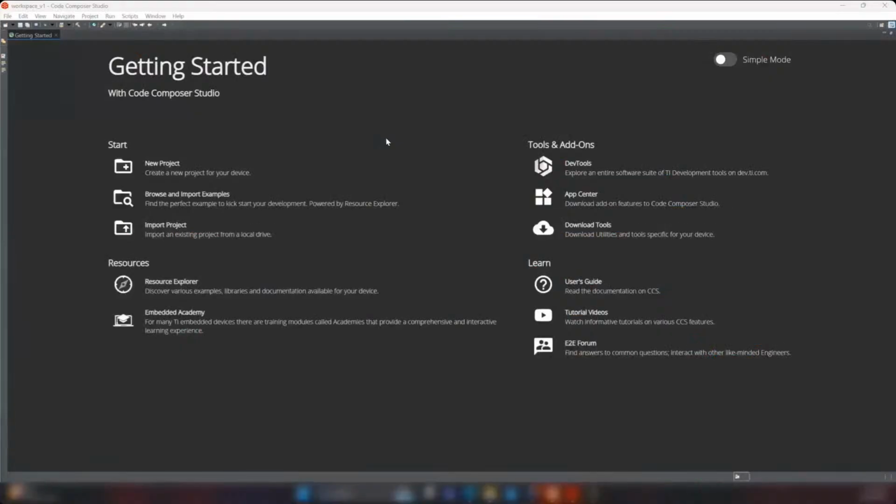In order to start using our subsystems, there are 3 things that you need to have at your disposal. First, Code Composer Studio, or your IDE of choice, downloaded. Here I have Code Composer Studio, and you also need the latest version of our MSPM0 SDK software development kit downloaded. This can also be found on ti.com, and we have included the link as well for everyone who registered today. The last thing you'll need is the MSPM0 evaluation board or LaunchPad, and today I will be using the MSPM0L1306 LaunchPad.